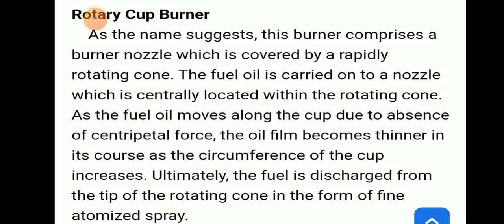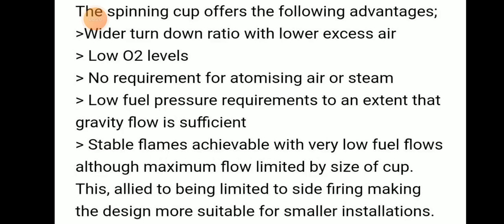Here the principle is that the burner consists of a burner nozzle which is covered by a rapidly rotating cone. Fuel oil is carried to a nozzle which is centrally located within the rotating cone. As the fuel oil moves along the cup, the oil film becomes thinner as the circumference of the cup increases. Ultimately, the fuel is discharged from the tip of the rotating cone in the form of a fine atomized spray.